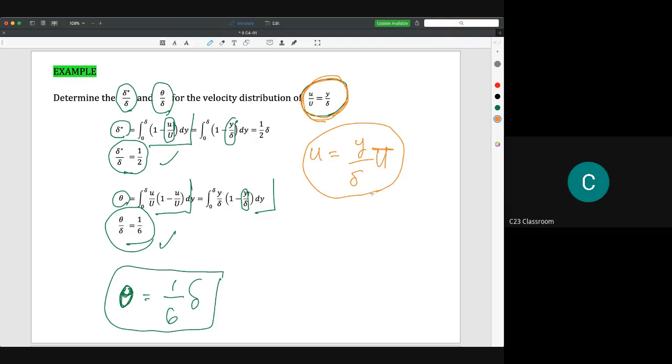I think this term of velocity distribution is quite familiar to you, because in the previous chapter we already learned how to derive from the Navier-Stokes equation until we could get the velocity equation u equal to y over h times capital U. But in certain textbooks they will write y over h with V. When we use the Navier-Stokes equation, we just focus on the velocity distribution and so forth, so the term might become a little bit different. So we have h sometimes and we have V.